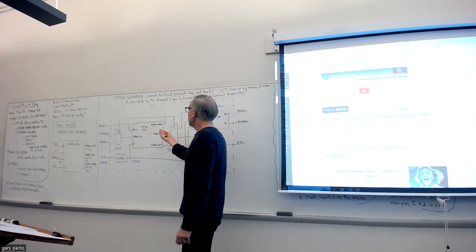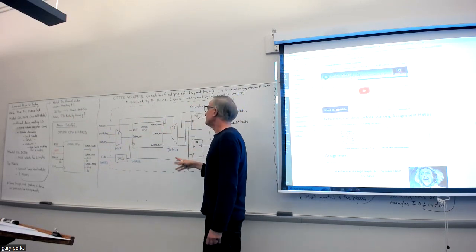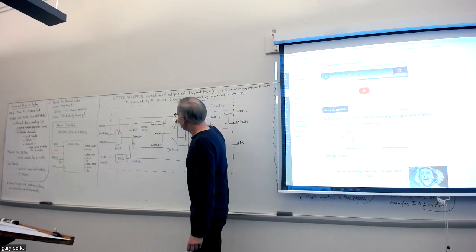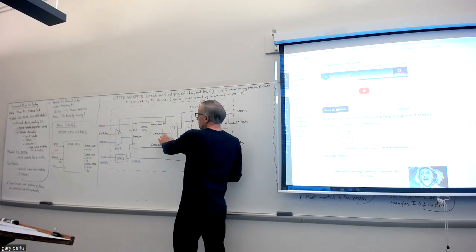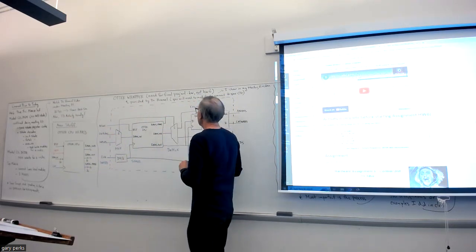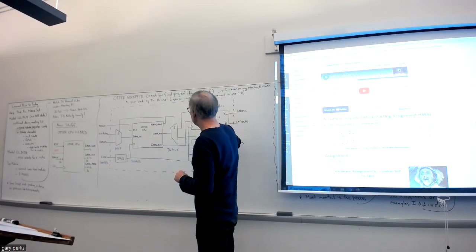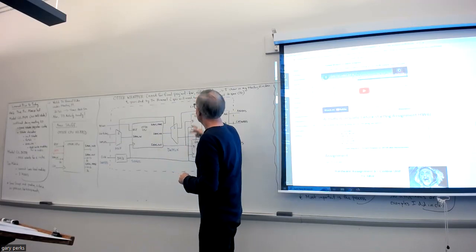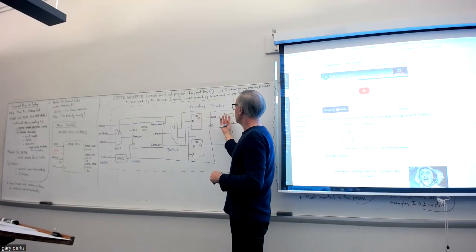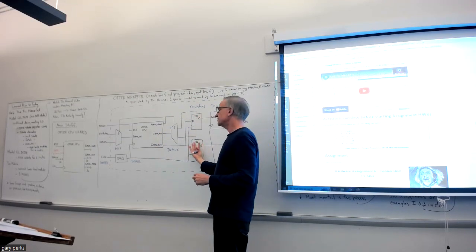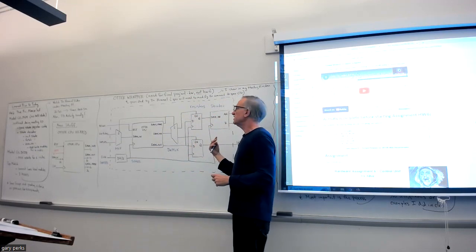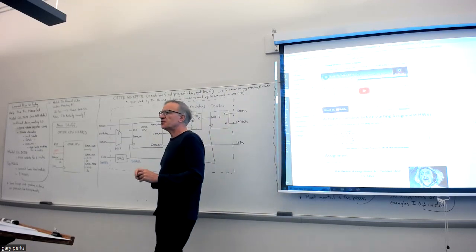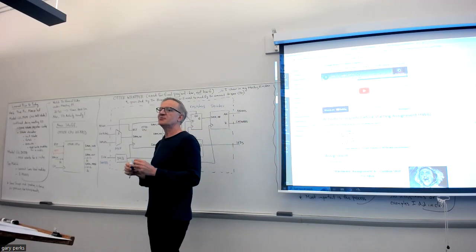Okay, over here on the output side with the DMUX, it's the same sort of thing. The address is what's connected to the select line. So the address is going to determine what this IO bus write output connects to, whether it connects to the enable of this register or the enable of this register. This register is holding data for the 7-segment display. This register here is holding data for the LEDs. So do you remember the address for the LEDs from your assignments?